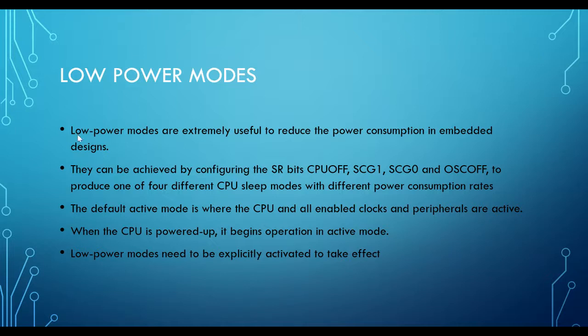So in order to be able to make use of low power modes, okay? Low power modes are basically in the status register. Still remember what's in the status register. You have your flags, your arithmetic flags, okay? And together with these arithmetic flags, you have 4 bits that are important to define what mode you are going to use. In the embedded system MSP series, they define several modes, called low power mode 1, low power mode 2, low power mode 3.